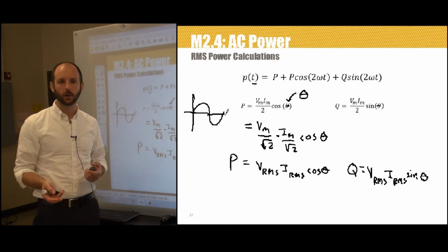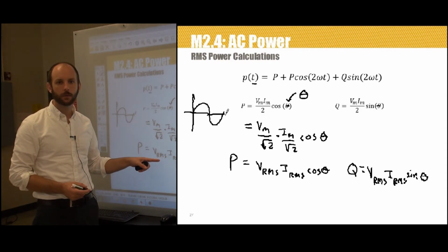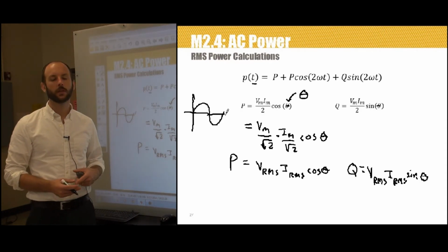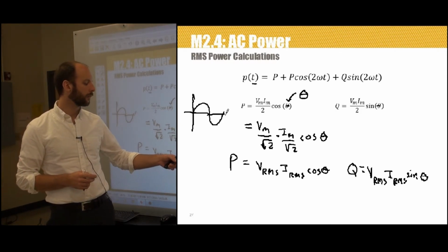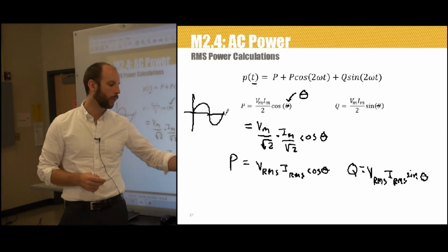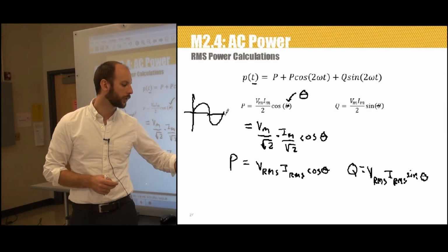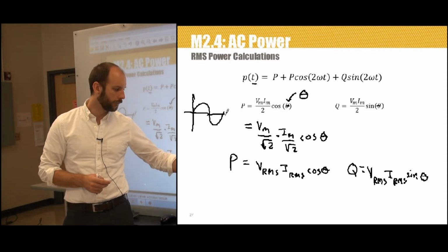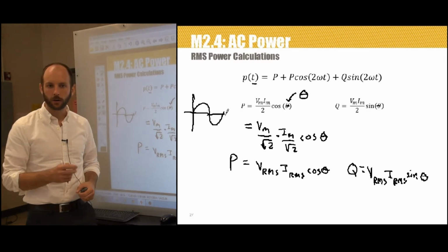Now what about an inductive load? Well, the average power here is going to be I RMS times V RMS times the cosine of the phase shift. We know that there's a 90-degree phase shift between the voltage and the current here. So theta V minus theta I is 90 degrees here. This term goes to 0. If I plug in a 90 here, sine of theta is 1. We get Q equals V RMS times I RMS. So we find that the Q of a purely inductive circuit is just V RMS times I RMS VAR,